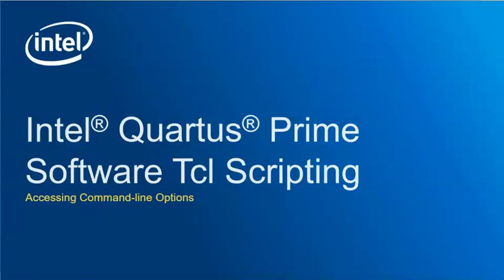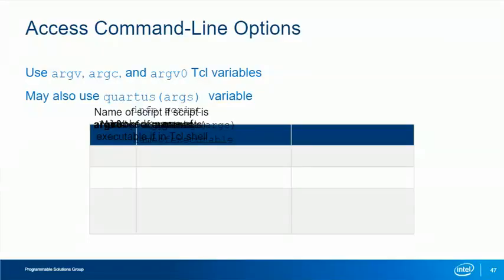Now I'll talk about ways to access command line options passed to Intel Quartus Prime software Tcl scripts. The Intel Quartus Prime software supports the global Tcl variables argv, argc, and argv0. Command line arguments are also passed in using the quartus(args) variable, so you have the option of using that as well if you wish.